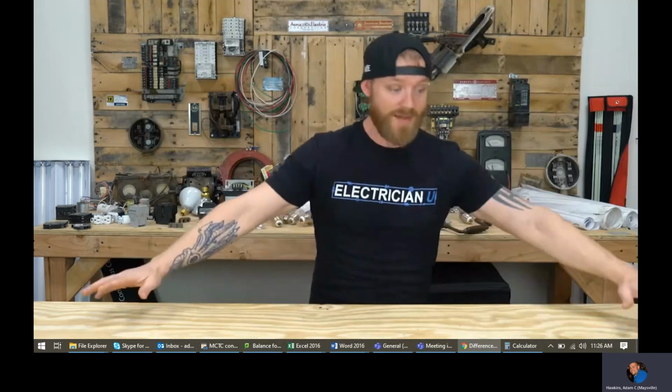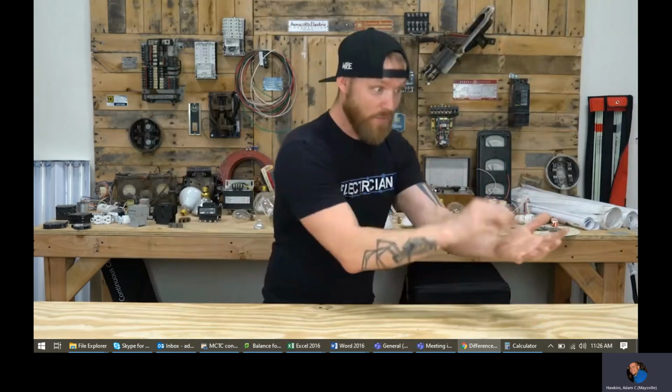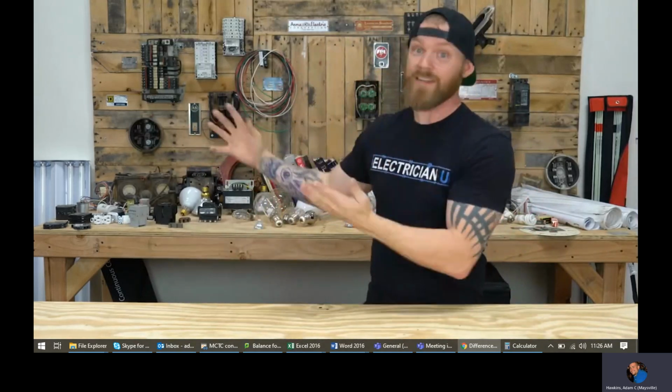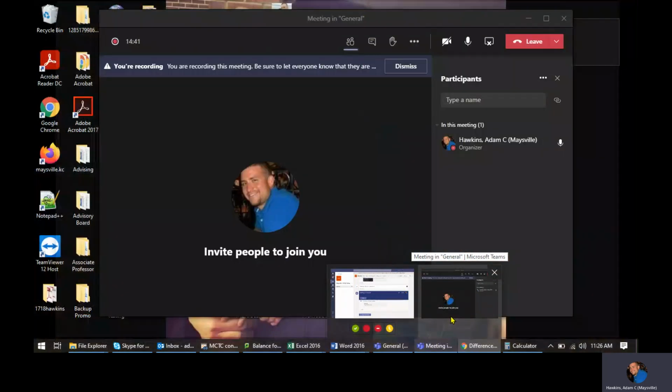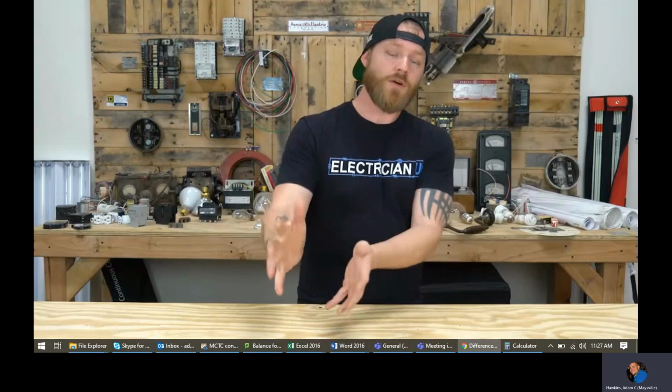So just know that if you're ever wiring a place and all of the specs call for 240 volt equipment, and you're reading nameplates on equipment, it's all 240, 240, 240, and you realize that your service is 208, you need to say something. You need to address that and figure that out, because that equipment is usually rated within 5 or 10% of its value. So if you overdrive or underdrive those motors, you're going to burn them up over time. And something like a $200,000 CNC machine, that's really, really important to know. So that's pretty much it for the 250 volt and under voltage systems.